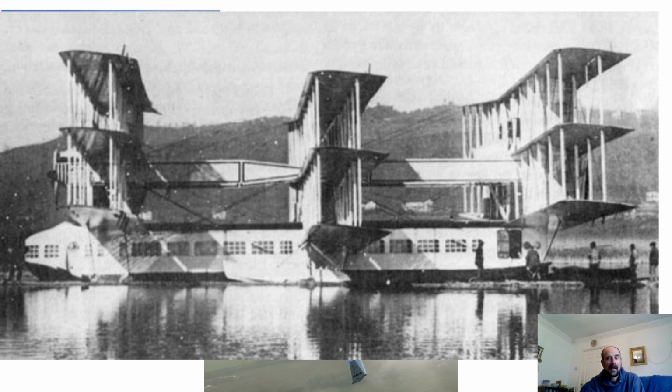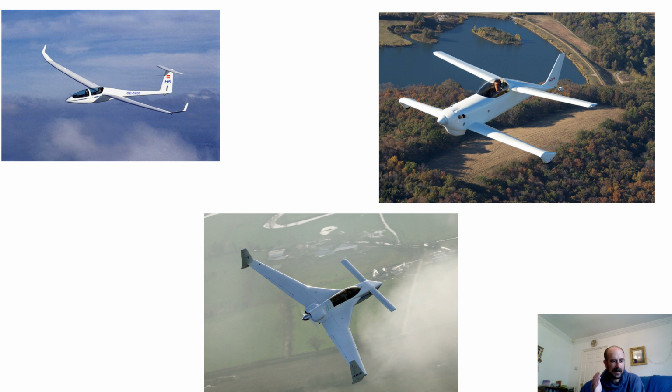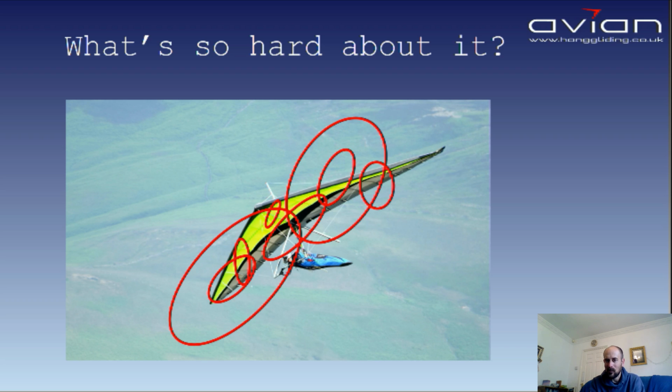So I've explained how conventional aircraft can generate pitch stability while still generating lift, also how tandem wings and canards do the same. What I've not described yet is how that works when you only have one wing surface. So rather than having the relative angle between your two surfaces, how do we do it when we only have a flying wing? Which of course is what we're getting to with hang gliders. That's the subject for the next video, but the clue is it still involves longitudinal dihedral.